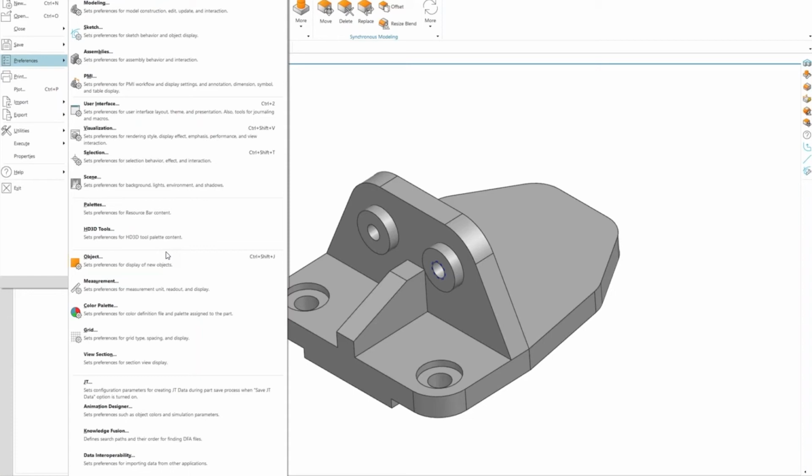And so you change the way something is being treated in the sketching environment for a part, but you don't do that in customer defaults. You're doing it in preferences. And so while you're working on that project and those parts, the way you have those preferences set will hold. But if you come back the next day or the next week and you start NX and you start a brand new part, those preferences in the sketch environment may or may not be there. Some of them seem to hold when I'm not expecting it, but most of the time, the customer defaults are the ones that stick. Preferences are the ones that stick for a little while.